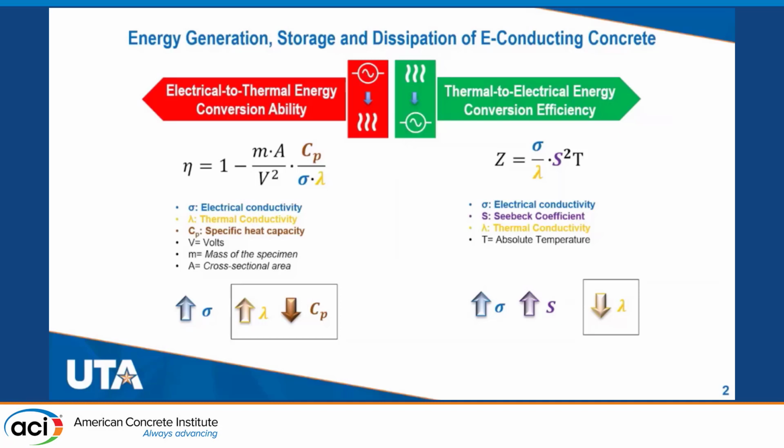However, when it comes to thermal conductivity, we see a change. For electrical to thermal energy conversion efficiency, we need to increase the thermal conductivity, while for thermal to electrical energy conversion efficiency, we need to decrease the thermal conductivity.